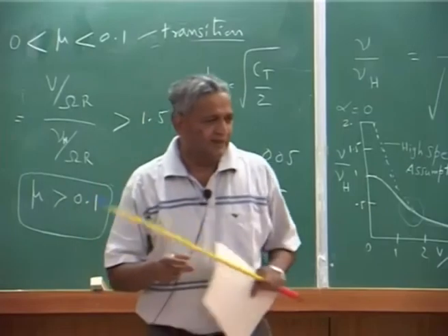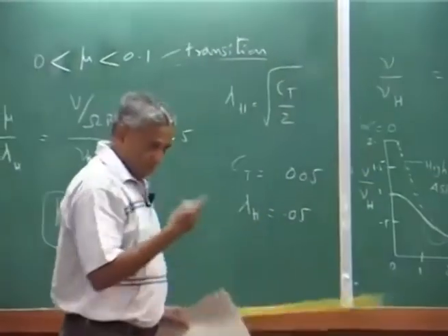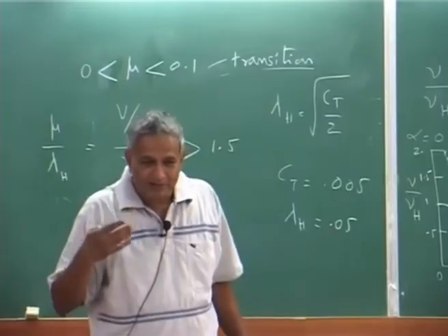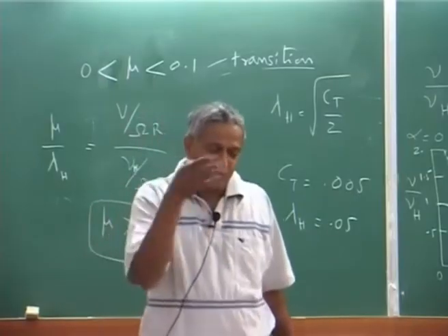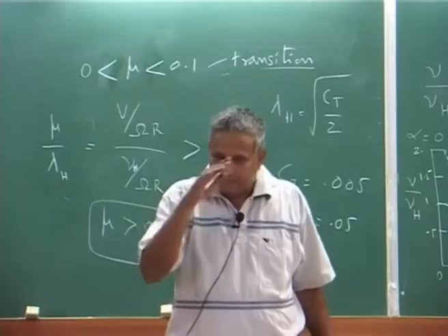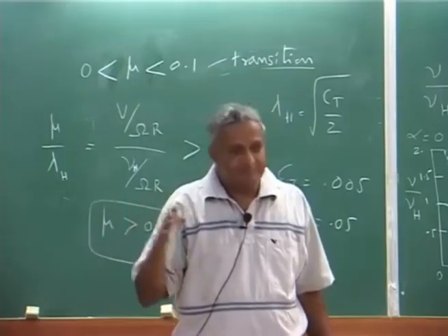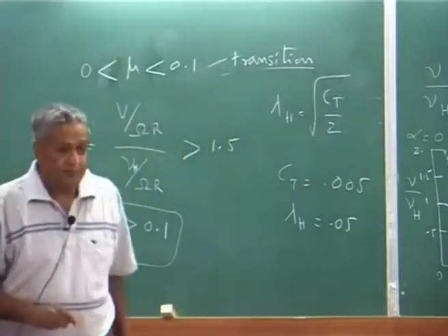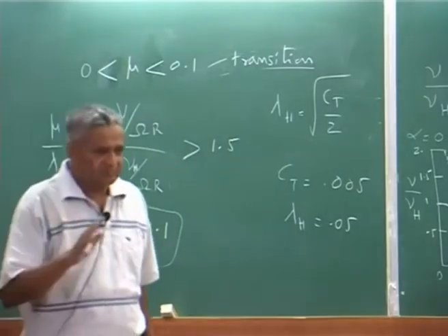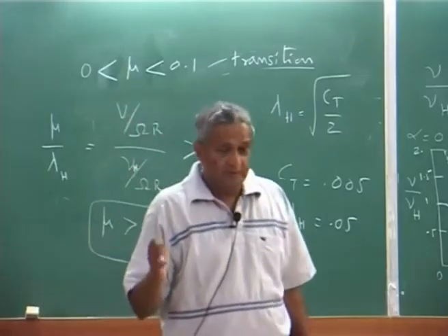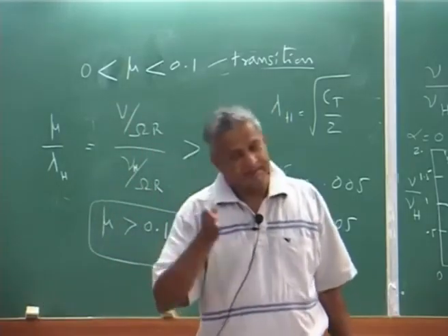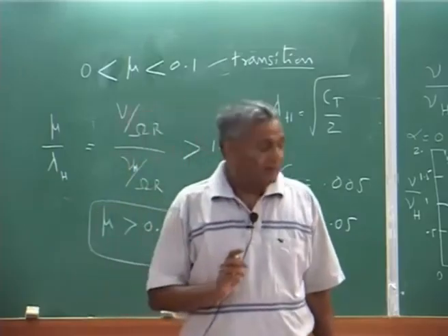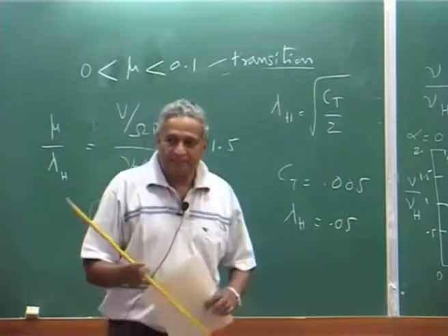Normally helicopters, you don't fly in this. Okay. Of course you have to, when you increase the speed you will be going through that, but you don't try to operate fully flying there. Okay. Later when you go to the power curve, if you want to fly at a minimum power point, it is actually beyond this 0.1, it is around 0.15, somewhere around that. But if you want good range, then there is another which is still further.